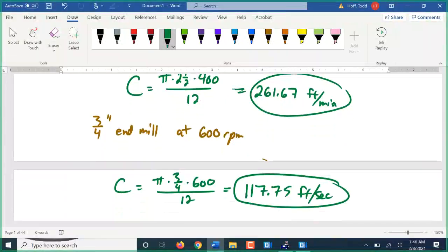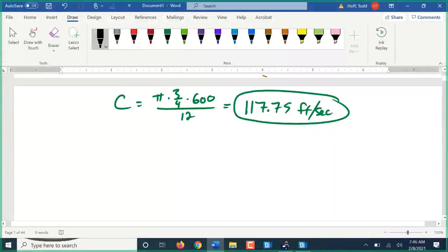Now, occasionally, you want to double check your setup to see what the surface cutting speed is. Most of the time, however, it goes the other direction. You know what you want your surface cutting speed to be, and that defines how many RPMs you should run the machine at, whether it's setting the lathe or the mill. You need to set the RPM for the machine.